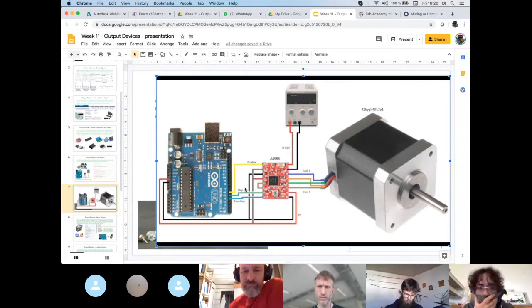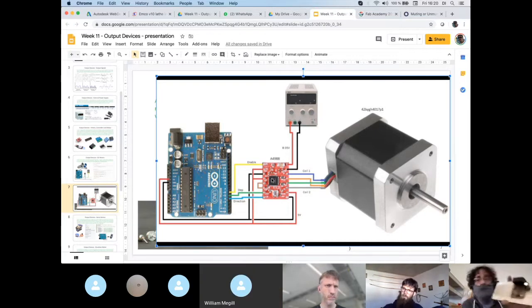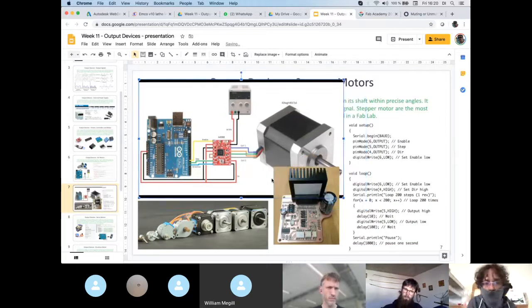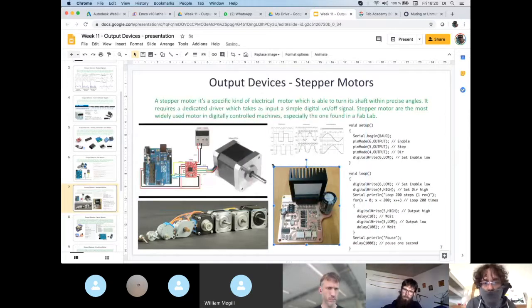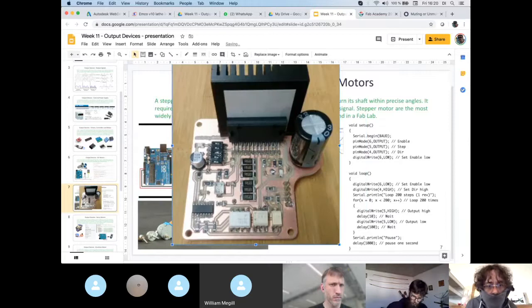In these drivers, not shown here, there is also a sort of trigger. In my case, just so it's easier for you to understand, this corresponds to these switches. You have these switches over here that you can move back and forth, and according to how you configure them, you configure the stepping mode.